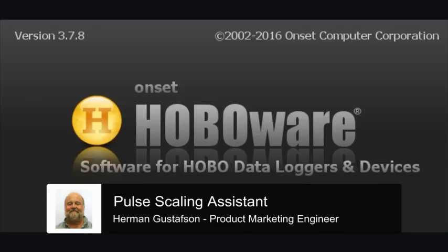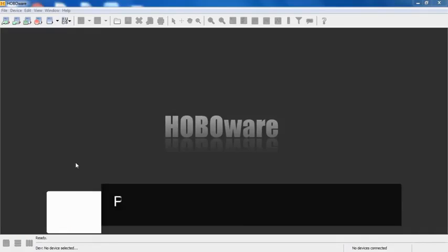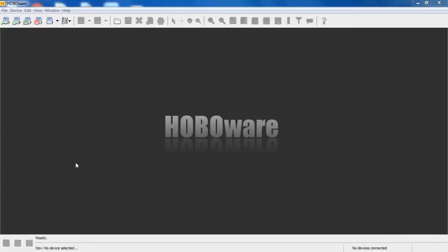This video will describe how to use Onset's pulse scaling data assistant software tool with both the free version of HOBOware and HOBOware Pro. The pulse scaling assistant, along with the linear scaling assistant, are software tools that are included with both the free version of HOBOware and HOBOware Pro. The pulse scaling assistant is used with loggers that can record pulses, or what HOBOware calls counts, from third-party sensors that generate those types of signals.